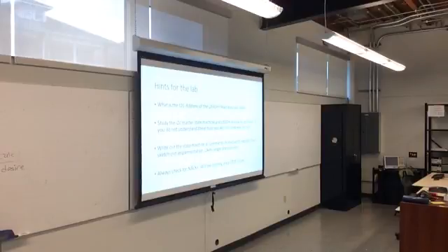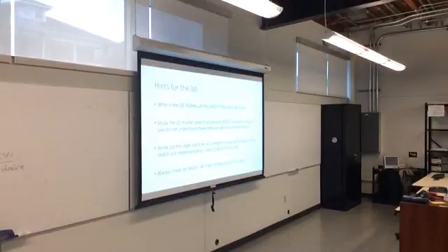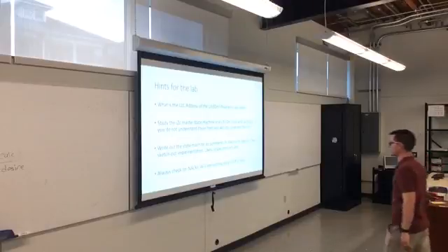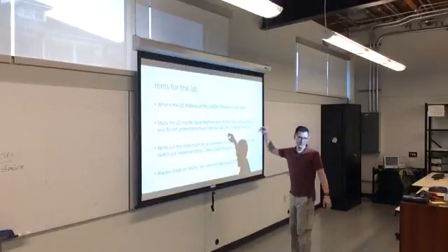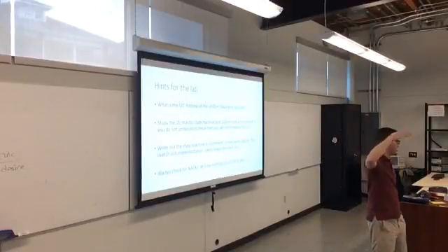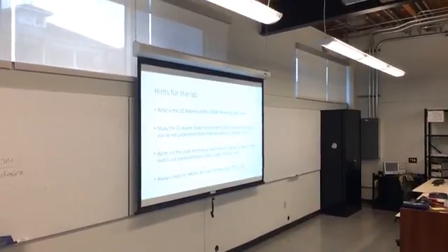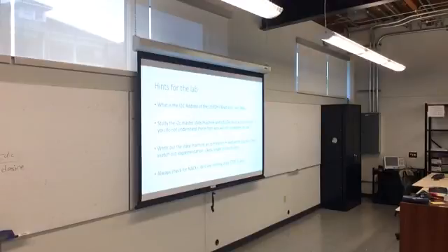My advice would be to take the read register function, the write register function, and for every action that you got to do, put a comment. And everything you got to wait for, put a comment. If it's something you got to do, that's a command, or that's a write to the transmit register. If you've got to wait for something, you're probably going to sit there and poll on that get status function until you get to the right state. So if you make line of code, line of code, line of code, and then walk through that state machine and it lines up, then it's going to be right if you put the right operations in the code.